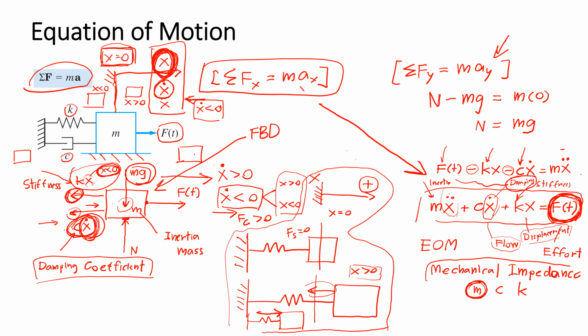The motor has a moment of inertia, and if you are interested in this, you may find some external source to read. But what I want to say is, if the motor has the moment of inertia of the rotor, it will be multiplied by the square of the gear ratio, and we can get the output inertia of the motor.